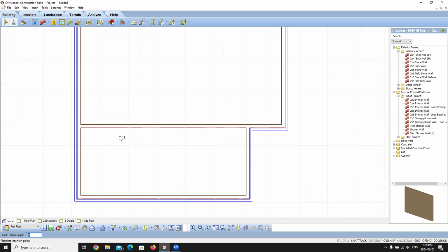So now we're going to be drawing some walls using the insertion offset option. So we're going to add in some walls. We're going to bring our mouse into our drawing area, and we're going to right click. When we right click, again, it's going to bring up a context menu. And in here, we have a couple of different commands. We have an insert by baseline, an insertion offset, and an insert from base point. We're going to use the enter insertion offset option.